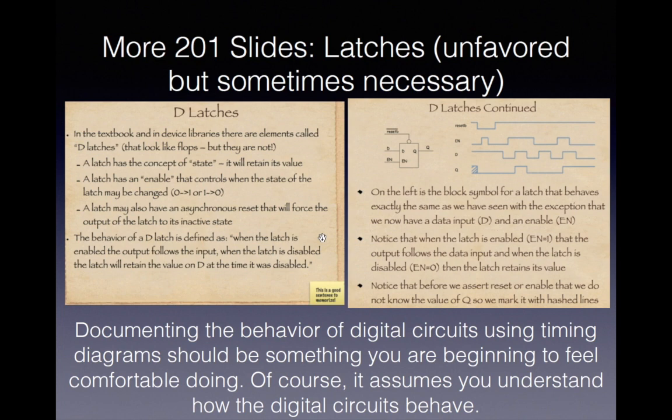The behavior of a D latch we should all have memorized. When the latch is enabled, the output follows the input. When the latch is disabled, the latch will retain the value on D at the time it was disabled. It will latch the D.